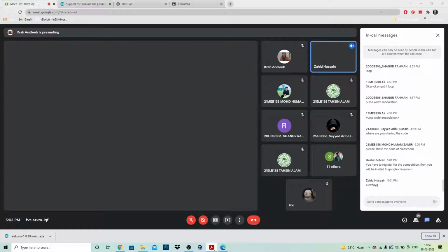These are just another way of writing the code. या फिर you can go this way of writing my servo attach, or you can define it this way, right? And this is doing the same thing. It's using a for loop to define the position, for writing the position, and it's incrementing the position value by 1 degree. So अब जितना भी आप यहाँ पे position value देंगे, it will correspond to 1 degree position. Like if you say 5, then it will correspond to 5 degrees.